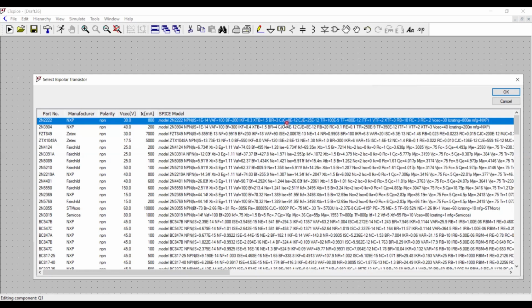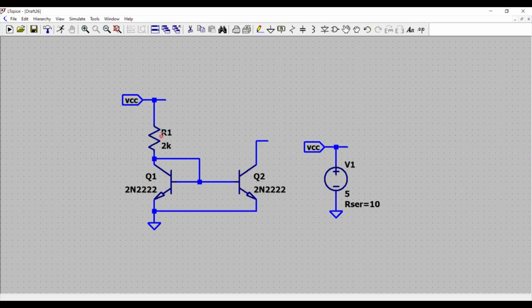Do I see the junction voltage? That is the turn on voltage of this PN junction transistor. 800 milliampere maximum current and maximum voltage across collector to emitter with base open. Anyways, with this done, let's say I have 5 volt divided by 2K. So that's the 2.5 milliampere current I am expecting to flow through this transistor. That is the collector current flowing through this transistor, isn't it?